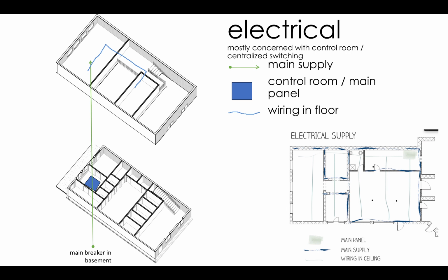Frequently, you will have a plumbing chase. You can sneak a lot of the major vertical cabling up there. However, things like the speakers that you might have, security systems, smoke alarms, smoke detectors, all sorts of things, wireless routers, those are going to need to go somewhere. Again, maybe this is what helps you decide you're going to have a ceiling as opposed to exposed structure or some alternative to exposing all of this misery.